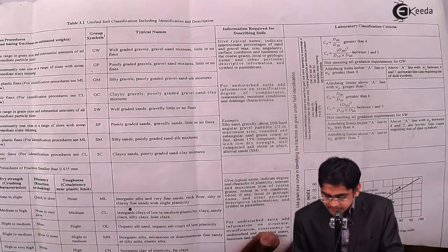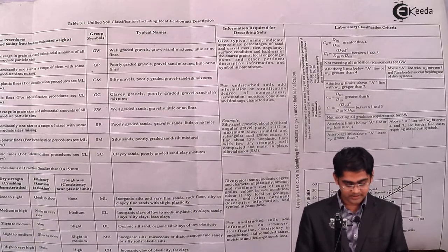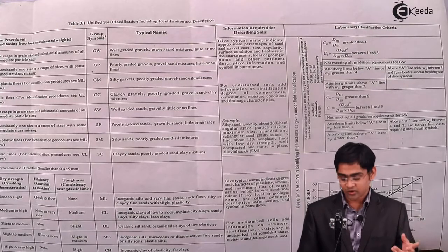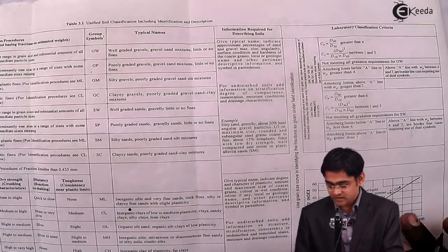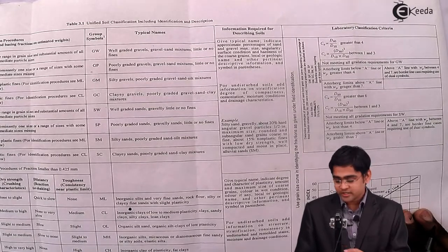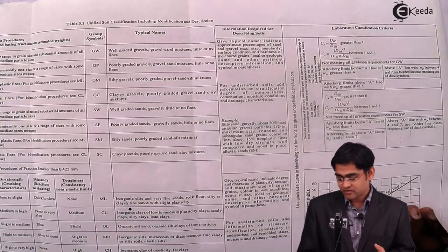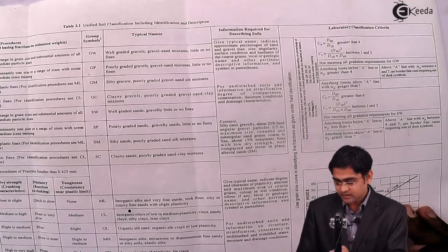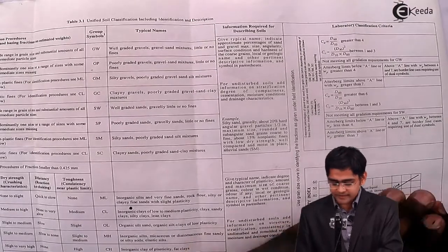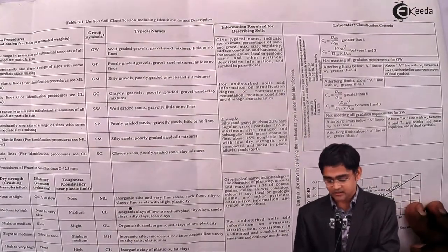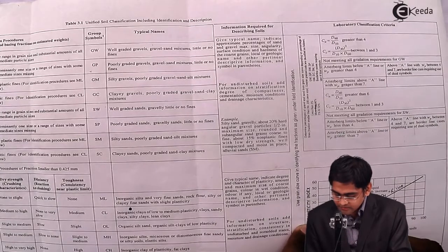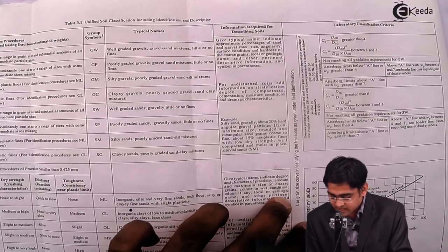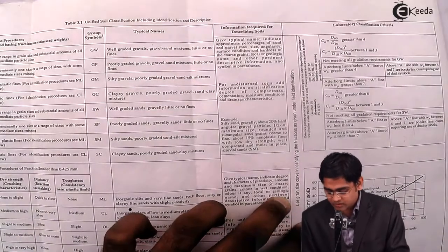If it has zero odor or zero spongy feeling, so this is particularly a lab test which you run on the fine-grained soils. If you don't smell a bad or vigorous smell, then you notice it might be a silt if it plots below the A line. But if it is plotting above the A line, then it is a clay. And if you have this particular region which is shaded in this diagram, then you need to give it the dual symbol CL-ML.